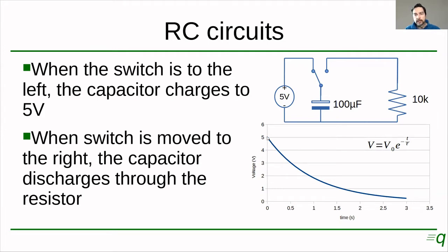So we can see that the voltage on the capacitor starts lowering, starts decaying, from the initial 5 volts to around 1.7 volts at the mark of 1 second. And after 3 seconds, the voltage remaining is very little here.